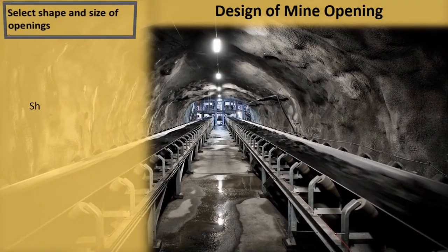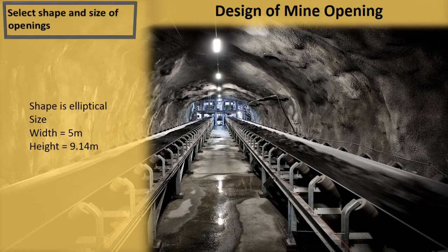For the design of mine opening, the shape we consider is elliptical and the dimension of the opening is 5 meter width and 9.14 meter height. Usually for salt mine, the elliptical shape is considered, while for construction purposes, circular shape of the tunnel is considered.